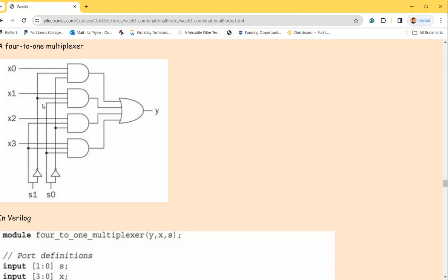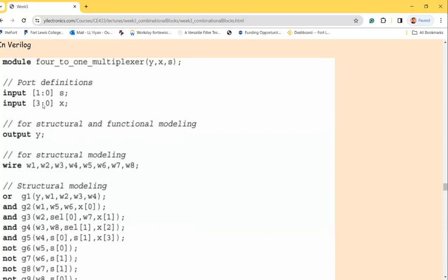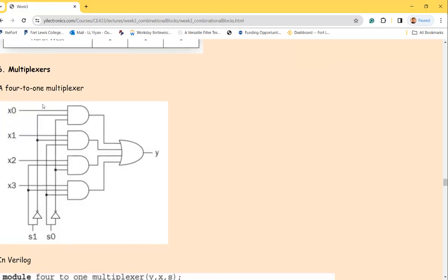So wouldn't you want to use behavioral modeling versus the data flow utility? For this example? In general? I'm playing around with the comparator. For sequential circuits, you just have to use behavioral.